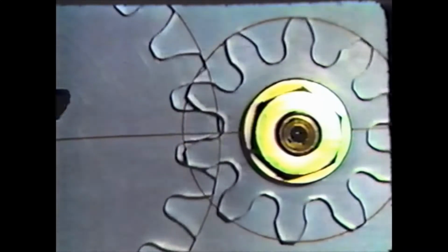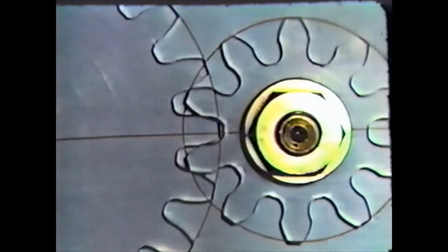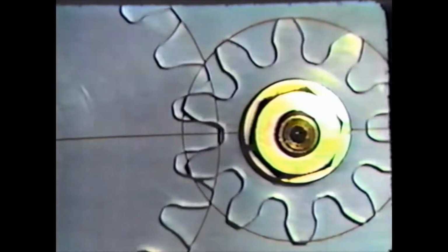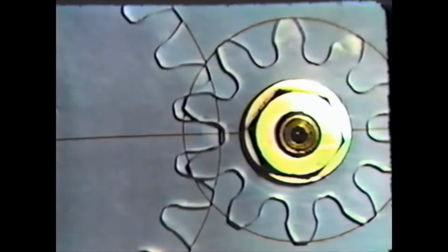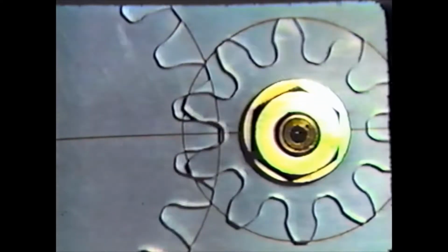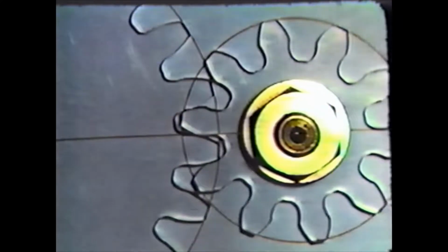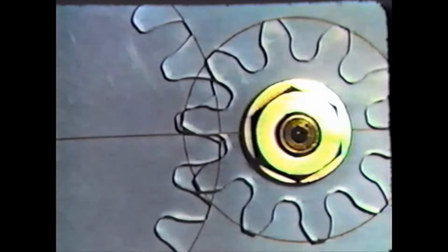Involute interference can be avoided in several different ways. One is to design the cutter to remove the interfering portions of the pinion teeth. A paper template of the original pinion located behind this undercut pinion clearly shows the alteration. The change in shape of the pinion tooth reduces its strength and removes a portion of the involute near the base circle.